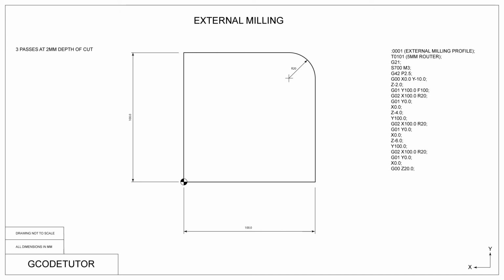Using a G00 command, we can rapid the cutter 20mm above the job. This gives us plenty of clearance when we're rapiding to the home position. A G28 command is an automatic travel to the machine reference point. We can also designate X0, Y0 to take it back to the tool change position and the machine home position.